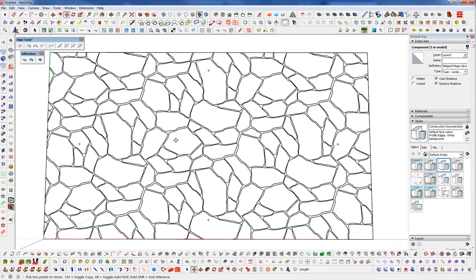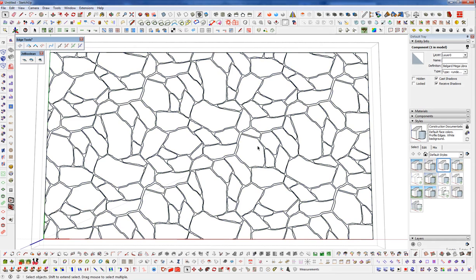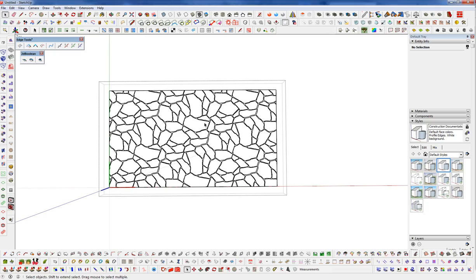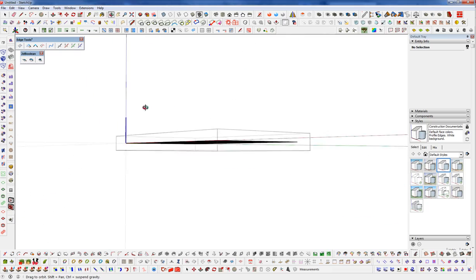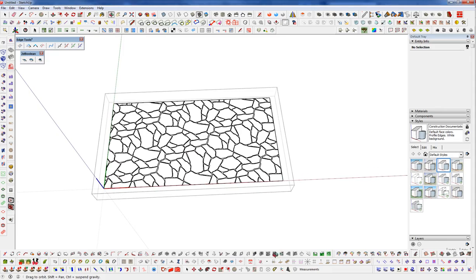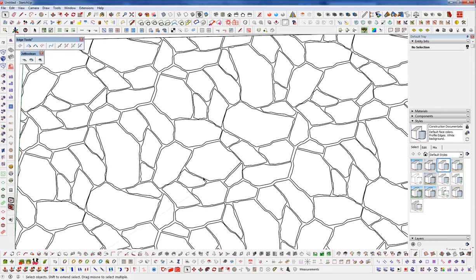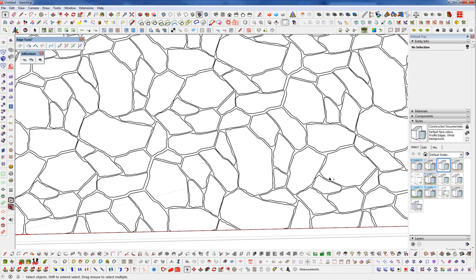And what I'm going to do here is, this is in a group, I want to open up the group, just by double clicking on one of these edges, and I'm going to use a plugin from TomTom called Edge Tools, and I'm going to use this to inspect all of the gaps in this DWG here that we've imported. Now if you look at it in SketchUp, SketchUp does a really good job of rendering these lines, and they look nice and smooth. There's good anti-aliasing going on, and it kind of makes it hard to tell with this style.